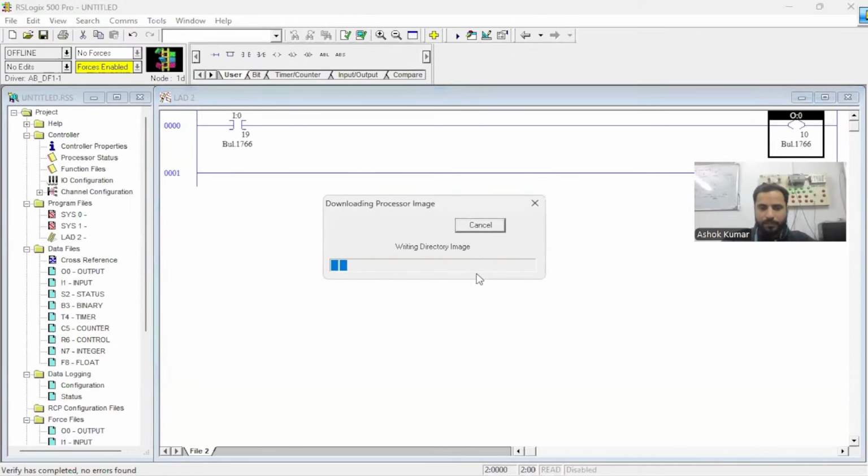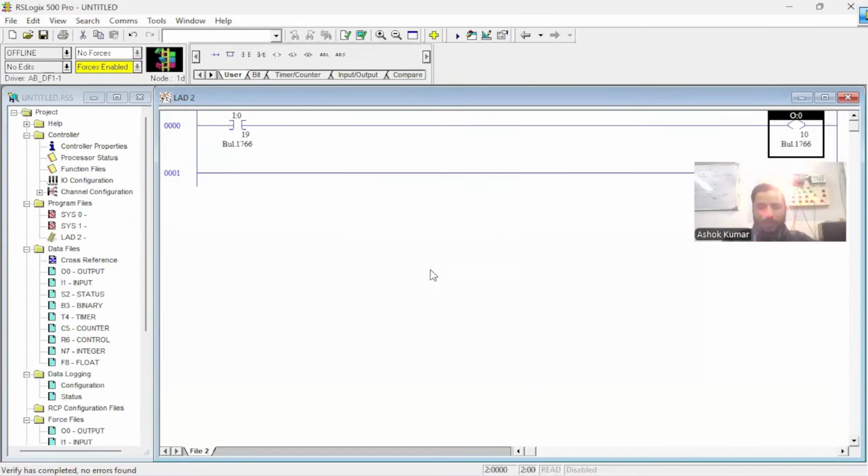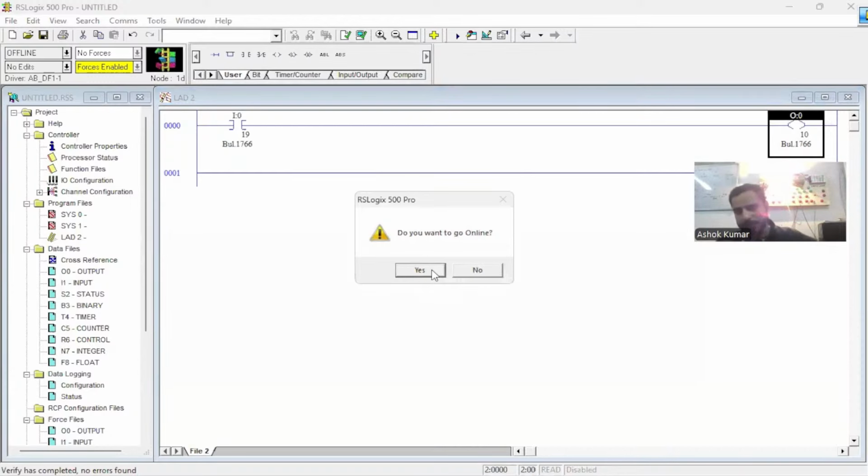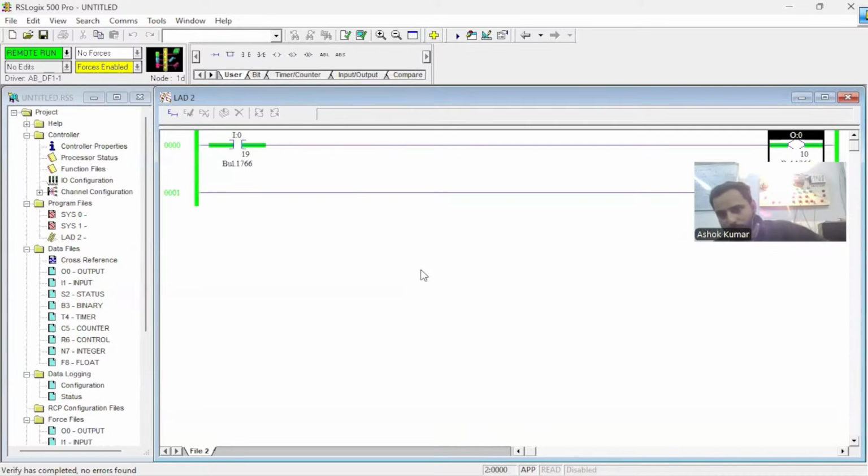The proximity sensor has different types. So this one is the metal sensor. It will detect the metal. Okay. So I need to put the metal near it and it will give us the output. I understand. And you may also see that on the back side, the bulb is on because this proximity sensor is working as an NC.